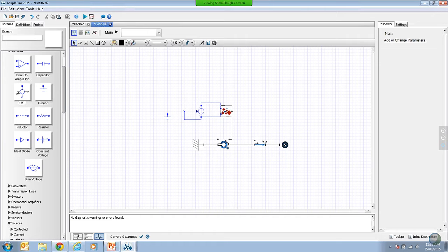In this case, I'm actually going to say that I want to control the voltage being applied to the motor so that it constrains the motion of the pendulum to within a specified angle. So I want to grab a constant from up here in the signal blocks. And I'm going to connect that to there and set that to 6.